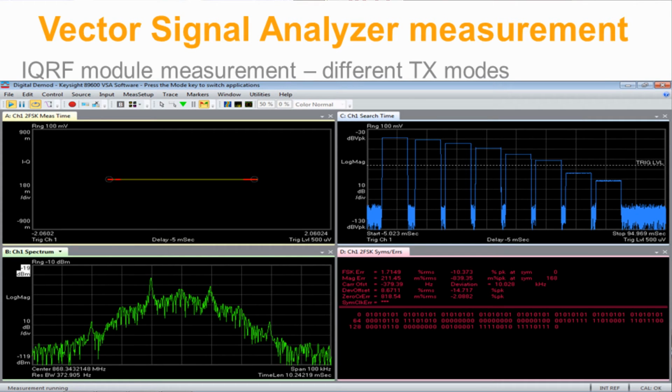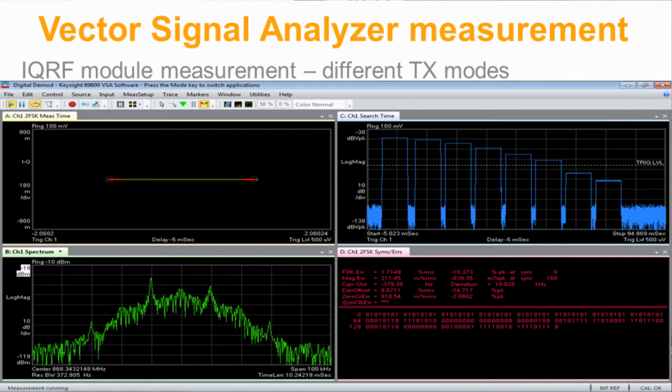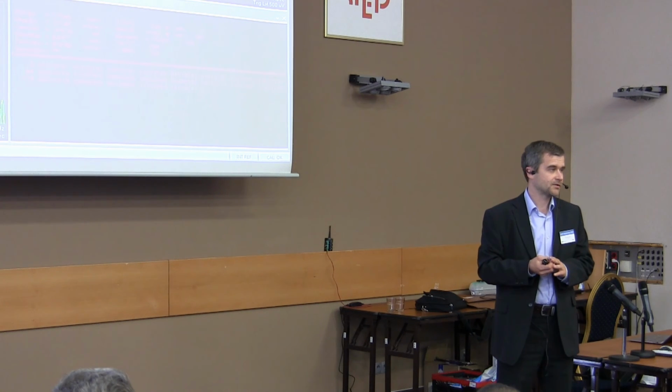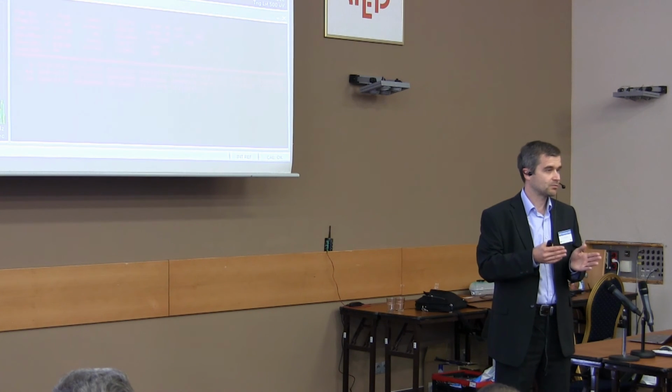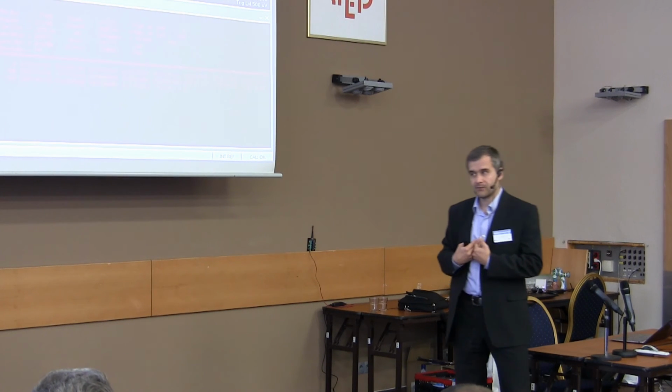The yellow line is the IQ diagram. In this case it's only a line, but it measures how good the modulation is. And hopefully visible, the red letters are the metrics of the modulation: modulation error, frequency error, or some offset, and the spectrum analyzer can also decode the messages you are transmitting to bits. So you can catch and record what you are transmitting.